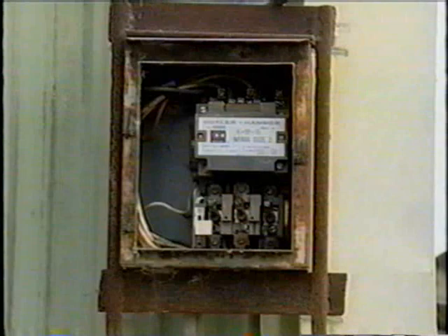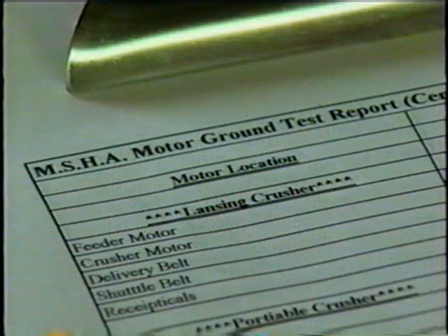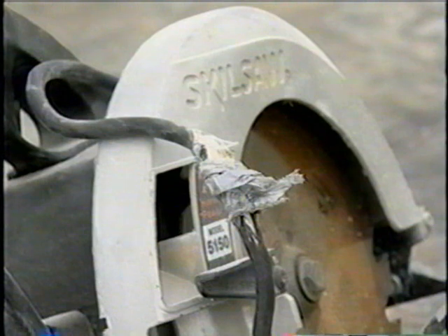slots and breaker boxes, lack of proper labeling of all breakers and disconnects, missing covers for electrical components, lack of continuity and resistance testing, non-grounded electrical apparatus, electrical tools with frayed cords, and missing ground prongs on extension cords.